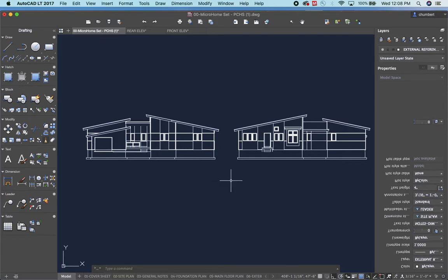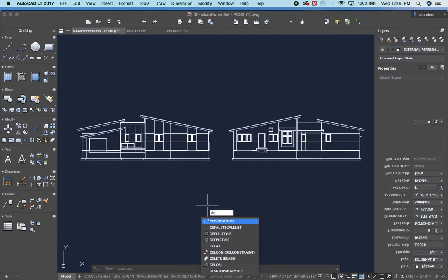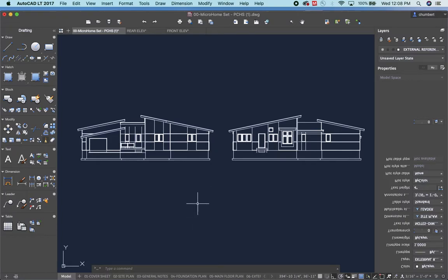Okay, the best thing I can tell you in AutoCAD, if you're not sure what a tool is, just start typing it. Rotate, and you're going to find out it's right there. And then you can just click on rotate. Okay, if you want to go like scale, you start typing the word, and there's the SC command for scale. Zoom is Z, and so you start learning. There's a few that I know by heart, but not many. But if you just start typing in your field here, I don't know if delete is even a command. It is. There it is. I usually just select and then hit the delete button. But almost any command you think of, if you just type it, will appear.